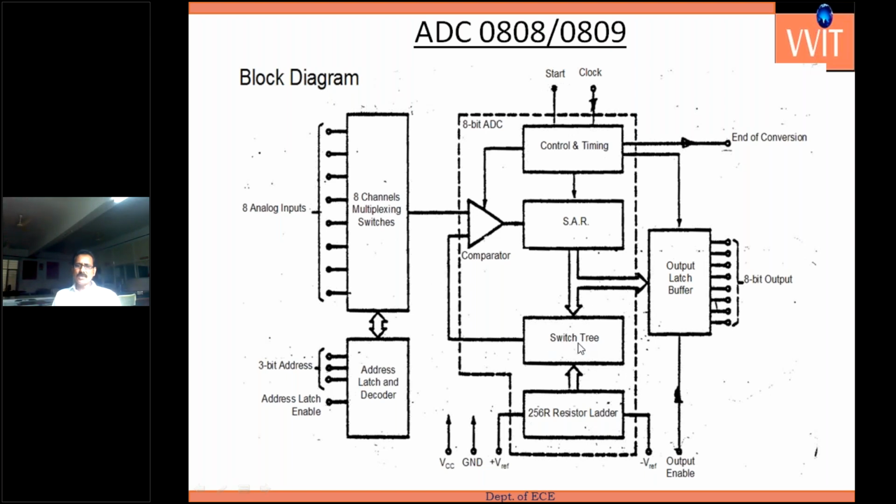All ones is the reference voltage indicated; for example, in the 8-bit 0 to 5 volt variation of the analog signal, 0 is indicated by the binary sequence 0 0 0, and 5 volts is indicated by all ones. The 0 to 5 volt range is sampled into 256 samples of the signal. 5 volts divided by 256 gives one sample step. Corresponding to the binary samples, we get the output signal. This is the indicated ADC conversion.